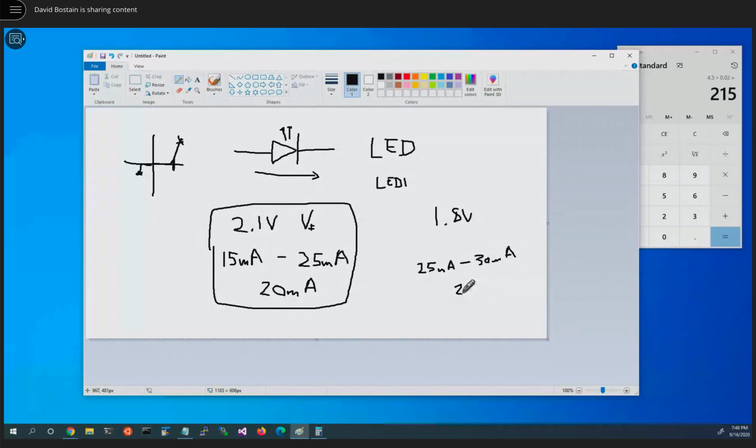Yeah, 27.5 milliamps. That would be a really hard one to design for, because unless your resistor was very precise, it's going to be easy to go over or under. Remember, of course, your LED, the resistor is limiting the current, but you can only use the ones that exist. So even though you find you can get everything perfect with a 123 ohm 5% resistor, there ain't no such thing as a 123 ohm resistor. There is, but they're not in the ones you're allowed to pick from. They're too expensive. So this is how we would do this.